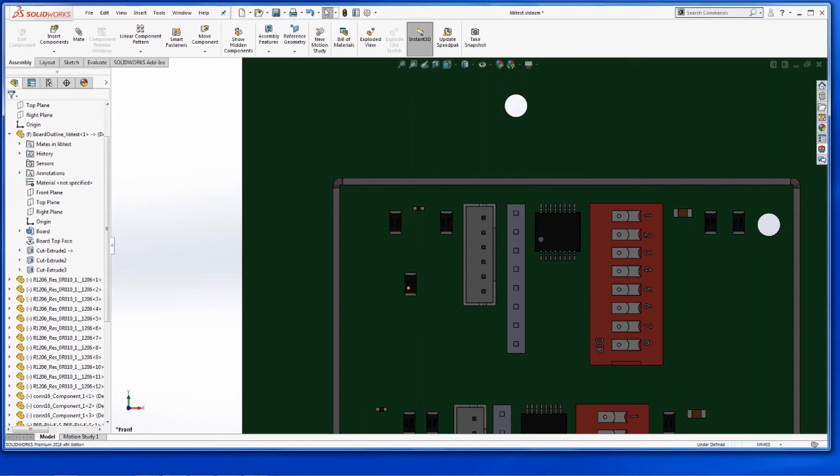However, I know I can move models all day long in SOLIDWORKS from the top of the board to the bottom of the board. That will not correspond back to the PCB layout. The PCB layout controls the surface placement. So if you need or have parts on the back, you would put them on the back first in SOLIDWORKS PCB or Altium Designer.